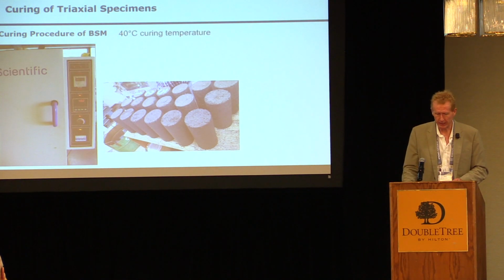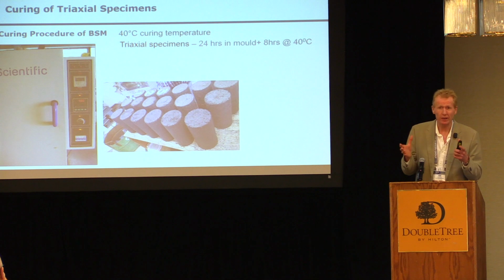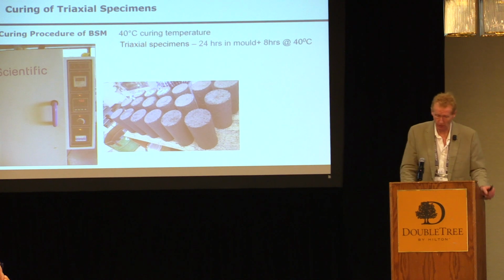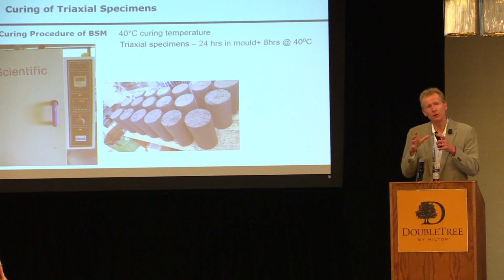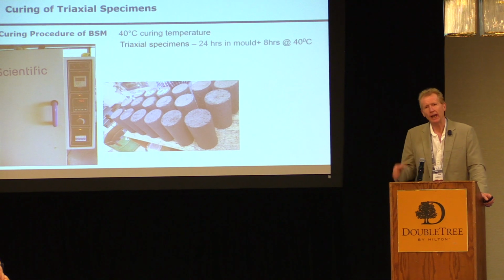Still 40 degrees, but here we keep it in the mold for 24 hours. So this allows, you've got to have enough molds for the mix design. That's important. It allows the material to strengthen before you take it out of the mold. Then you need 8 hours.